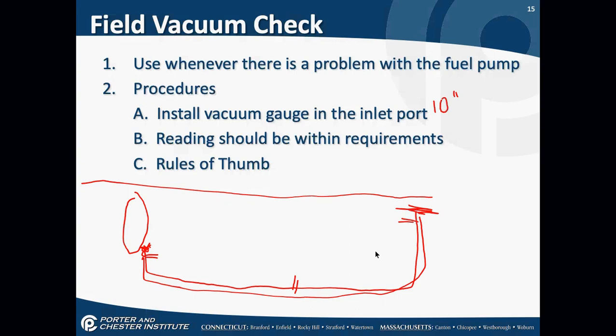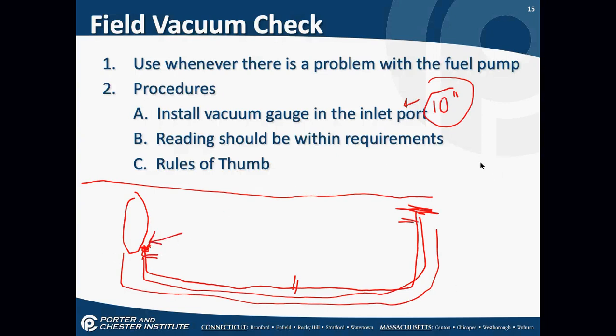So if I install a vacuum gauge on this inlet port, by the way, there's 2 inlet ports on your oil pumps, and I run this vacuum, eventually it should have the same vacuum or close to it that was just on the pump, because I'm pulling on this. I have a valve closed right here. When I shut my pump down, it should hold that vacuum. If this vacuum releases on this line, I have a leak someplace.